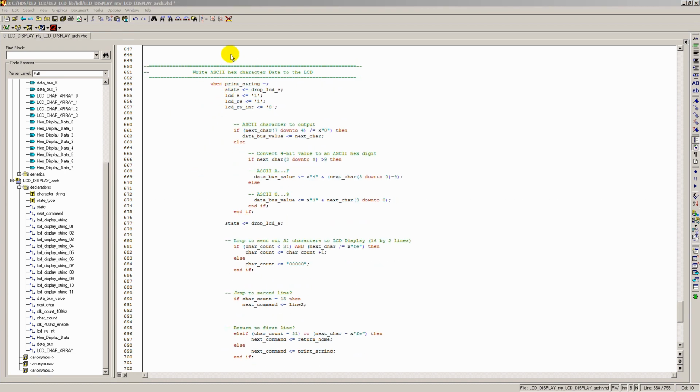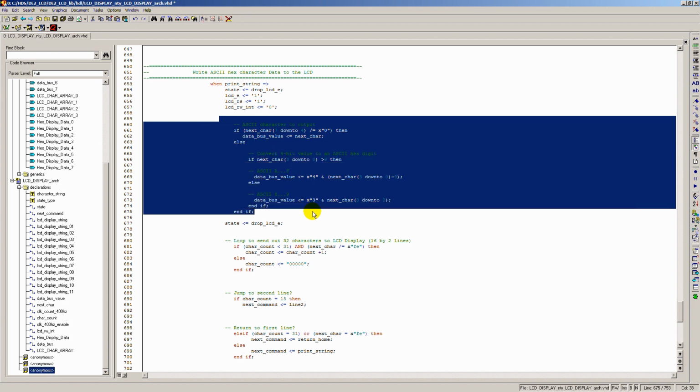So essentially in this area of our VHDL code, we're beginning to send hexadecimal values, character values, or character data to the LCD display. There are particular if-then-else statements that we use here to control the conditions of a series of input switches that we have declared to control essentially 2 separate characters that are used instead of, say, hexadecimal variables within a string.